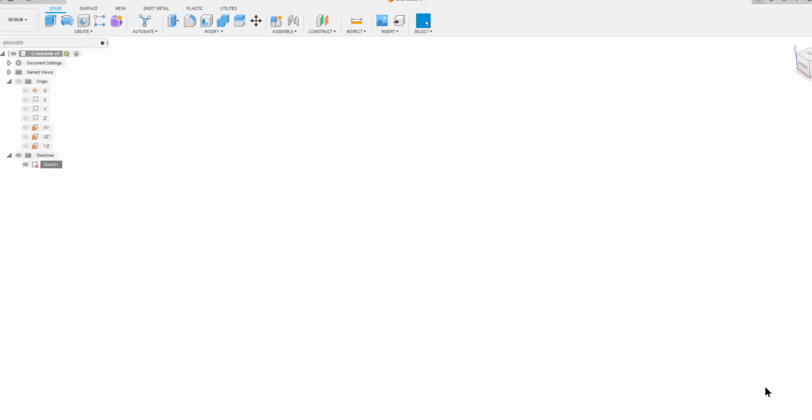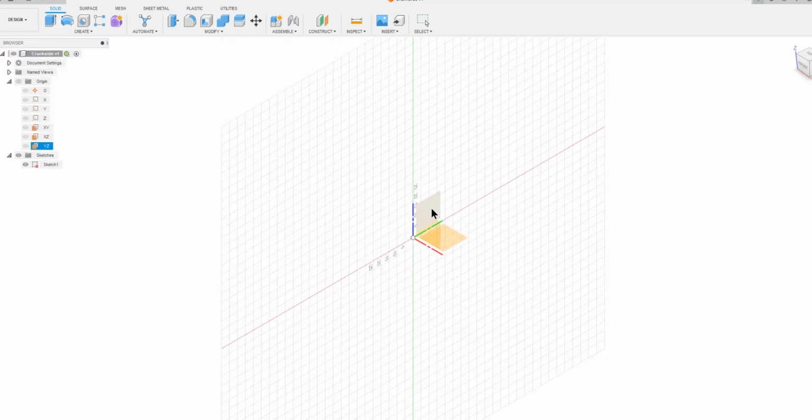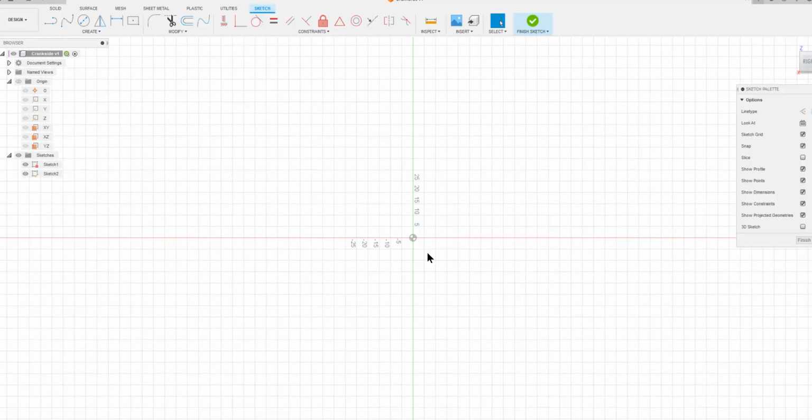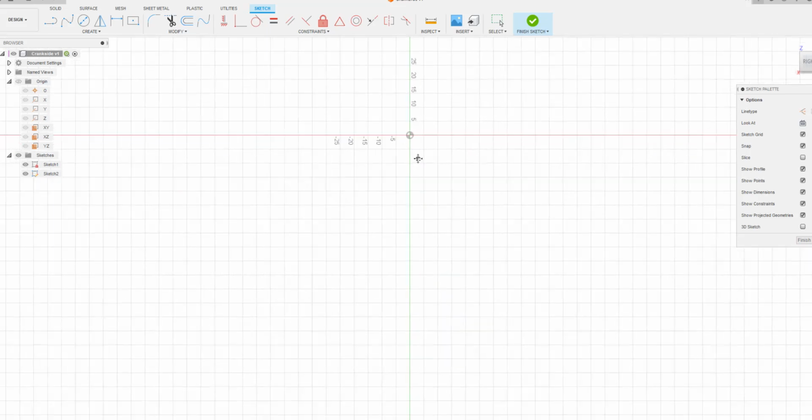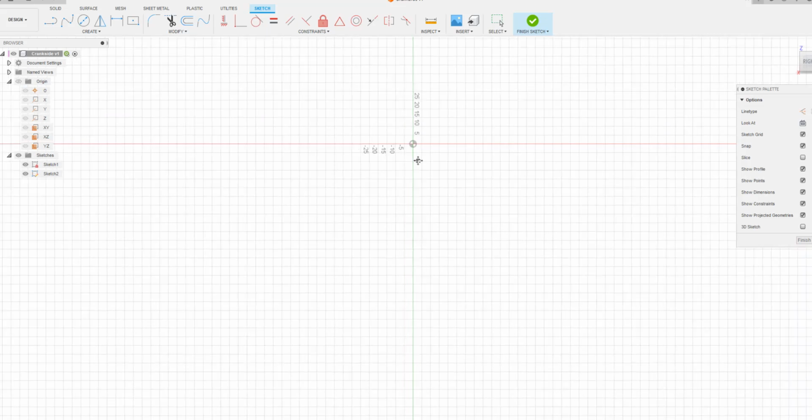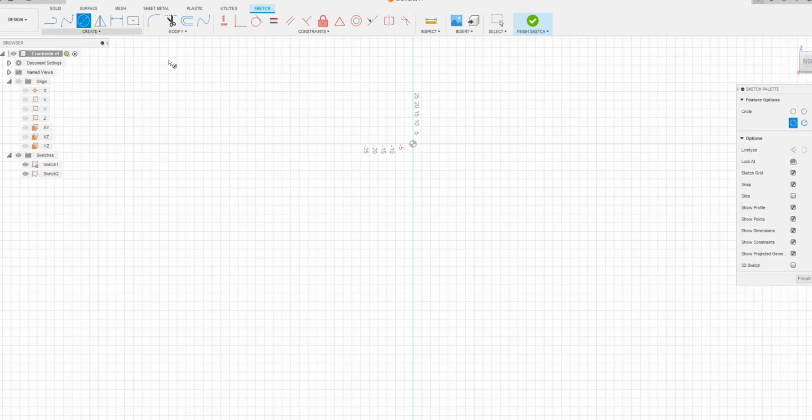In order to make the crank side, I want to begin a drawing by choosing create sketch. I'm creating that sketch on the YZ plane. As I create the sketch on the YZ plane, I like to pan up a little bit, and then increase the density of what I'm using to have more of it on a smaller piece on the screen.